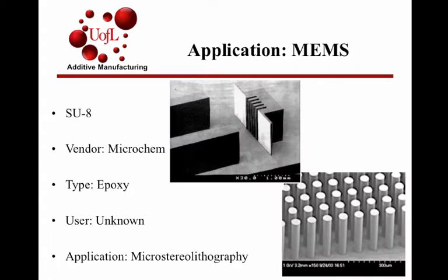As we go to the second part of module 2, we will see that there is a lot of careful analysis of reactions and protocols for characterizing reactive polymers, especially using SU8 as one of the types of epoxies for photolithography applications. This provides an important avenue for being able to create much smaller features. You can see that these pillars are roughly in the order of about 10 microns.